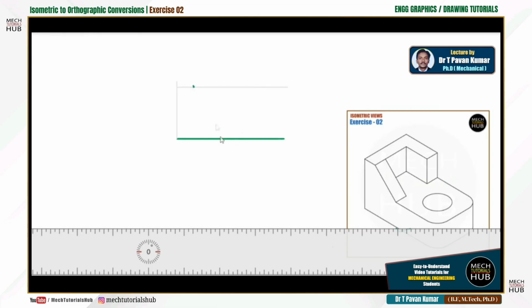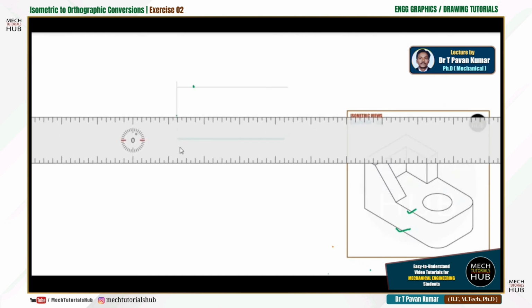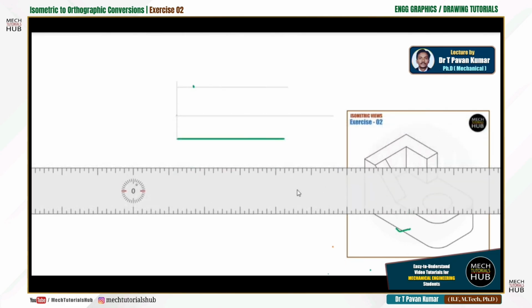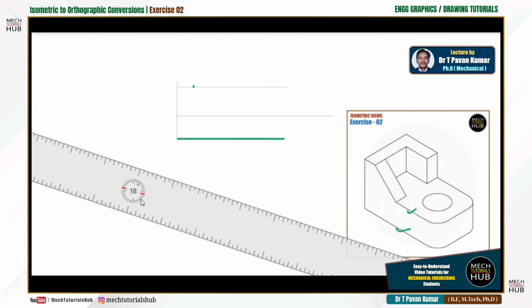This is fine. Other than that, from here there is one more parallel line, this line, which is starting somewhere here. So I'll make a mark of 20 here, place the horizontal scale properly intersecting with this intersection, and draw a 2H construction line. You can draw any number of construction lines according to your convenience. At a later stage there is no need to erase also. You can make use of these construction lines to darken the complete sketch whatever you have drawn.